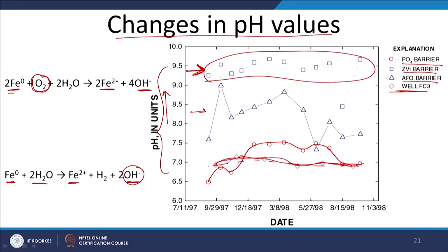So, depending upon the issues with respect to pH change downstream, you can look at relevant remedial measures. But typically, if you are trying to balance between the uranium removal, which is almost 100% in the zero valent iron PRB, and the pH change of 2.5 units, and again you are going to have dilution later, that is reasonable. So, let us move on.